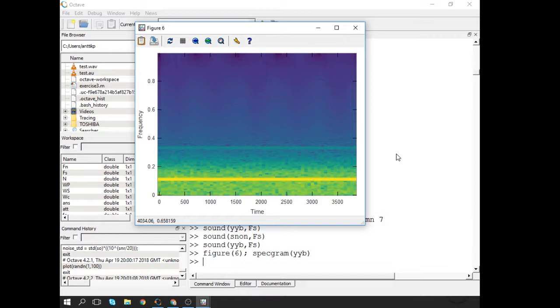It was a low pass with the cut frequency at 1 kilohertz, so it doesn't affect our 440 hertz. But then the third harmonic is already on this downgoing slope, so there's something like 60 dB attenuation, which is enough for us. So the human ear, basically the total dynamic range is from around -20 to 100 dB without damage.